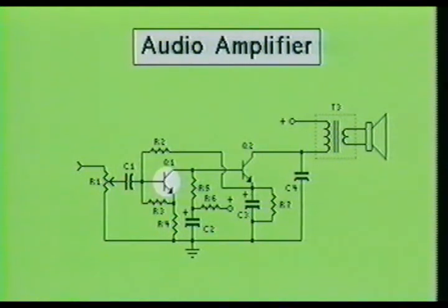Transistor Q1 is basically used as a driver or preamp for transistor Q2. Transistor Q1 variably pulls down the control line going to transistor Q2 according to the audio modulation impressed upon Q1's base. Transistor Q1 is of course direct coupled to transistor Q2.